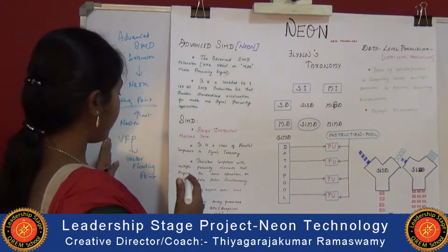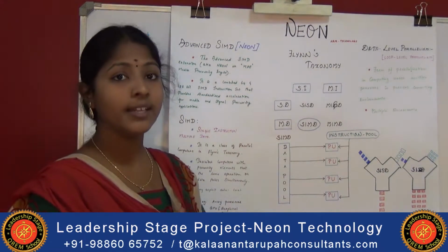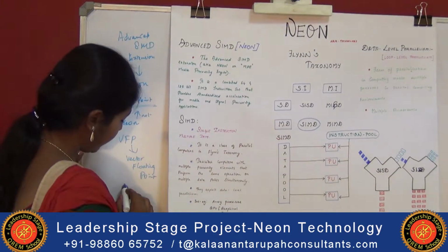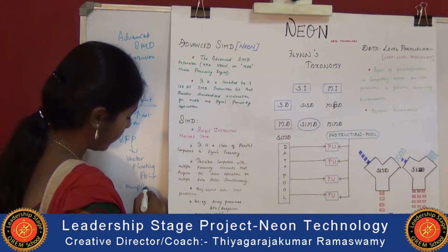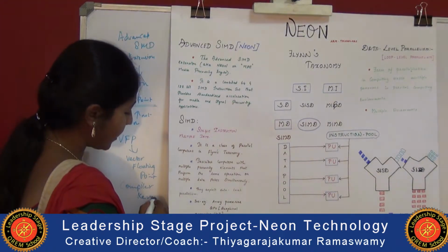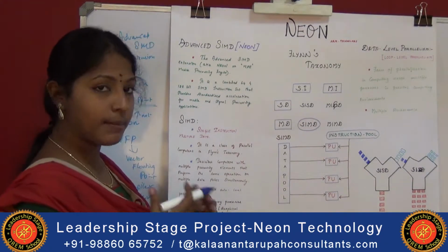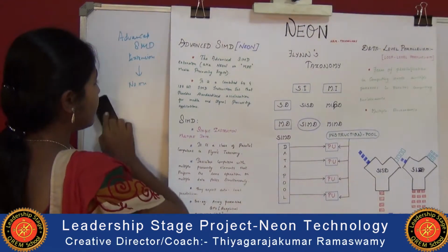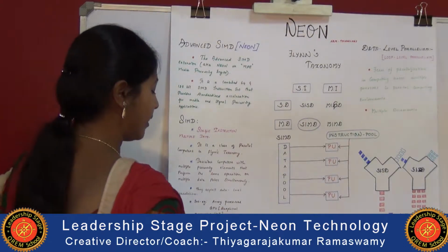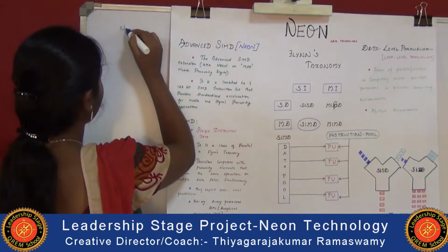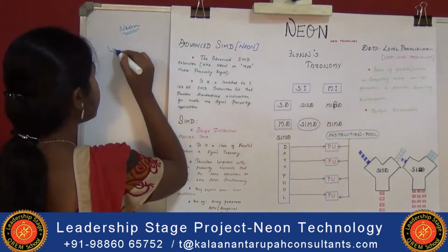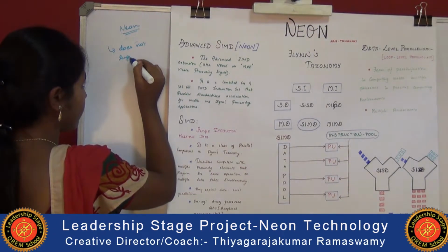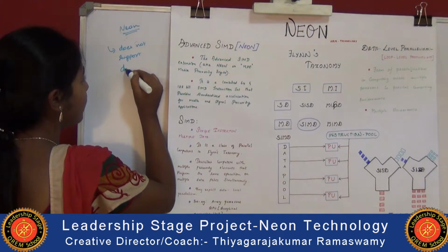So these vector floating point and the NEON are different, and they use the same register space, but it can be taken care of by the compiler or a kernel. Even though it is different, it can use the same register space. That's about this VFP, and the main difference between this VFP and a NEON is that NEON does not support double precision floating points.